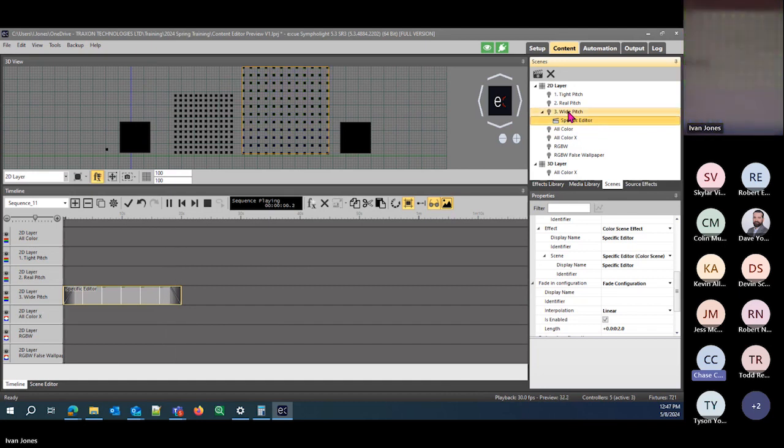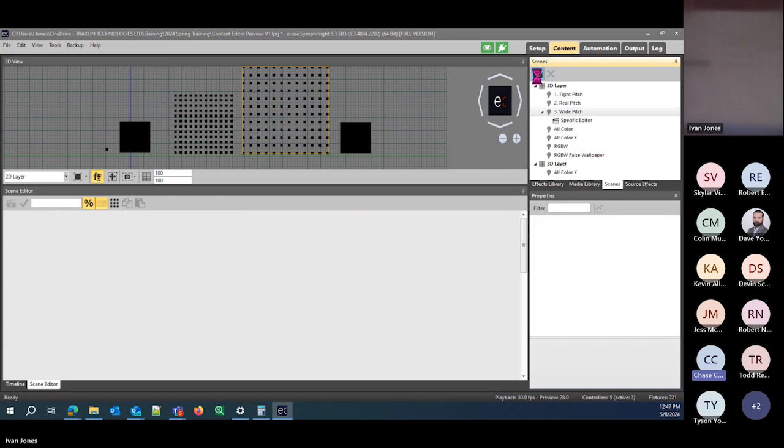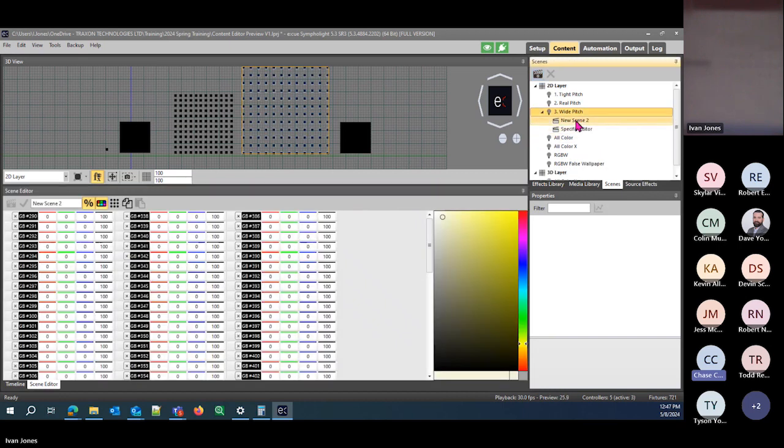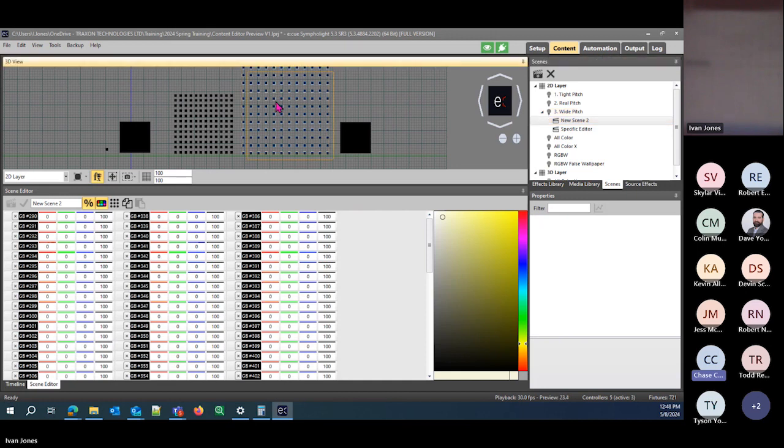Another place we end up using it are places where we might need to bring specific channels up to have operation or functionality with fixtures that don't maybe have standard profiles. So you could actually use intensity channels in an array if you wanted to, and patch those to specific channels for certain DMX controlled devices that need certain channels up to operate in different modes.